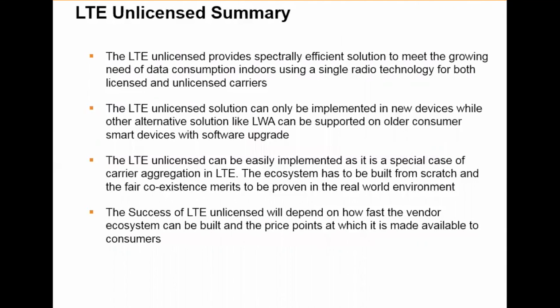In summary, in the last slide, the LTE unlicensed provides a spectrally efficient solution to meet the growing need of data consumption indoors. The advantage of this is it uses a single type of radio technology for both licensed and unlicensed carriers. Basically, this is just like a normal LTE carrier aggregation. The only difference is instead of aggregating two licensed carriers, I'm aggregating one licensed and one unlicensed carrier, but I'm